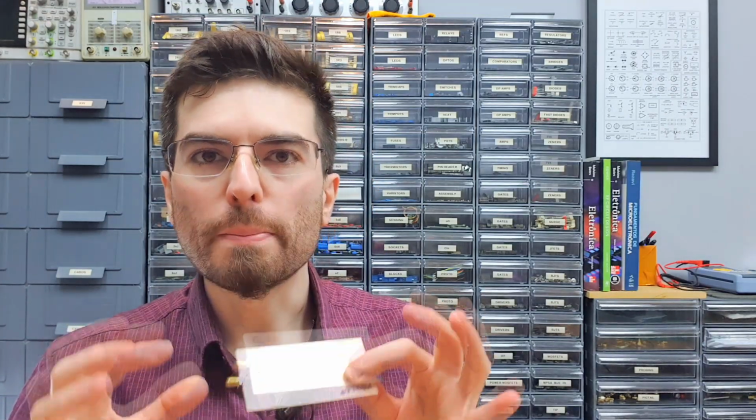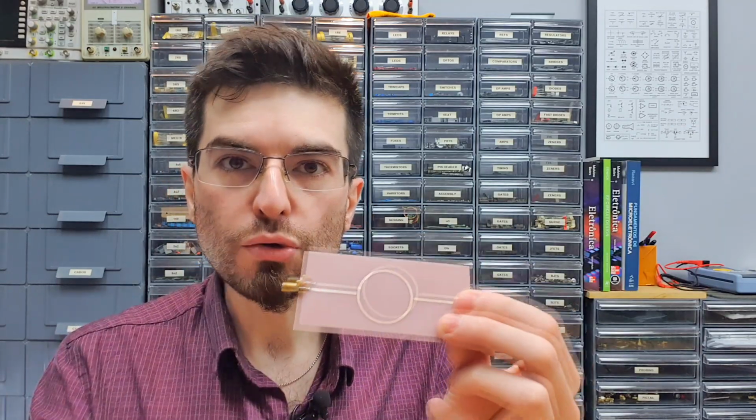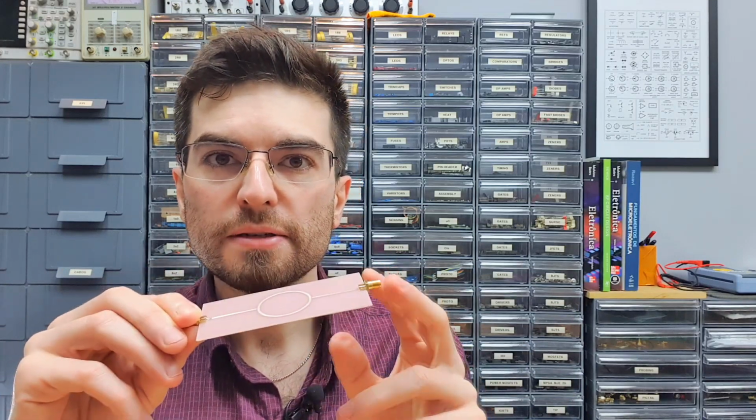First method we are going to explore is the ring resonator. Just to clarify what we are trying to do here, guys, we are trying to measure the substrate dielectric constant, or permissivity. I bought this PCB material for the projects of the channel and I don't know its dielectric constant. So we need to measure it to be used when we are developing and designing filters, resonators and things like this. This is 0.8 millimeters FR4 double-sided, as we use here on the channel.